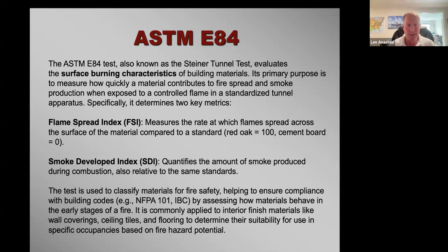And so what it does, you run the test and you get what's called a flame spread index, or FSI, and a smoke developed index, an SDI. These are the two criteria. For the flame spread index, the standard is red oak equals 100. I'm sorry, not 100 degrees. Red oak has a flame spread index of 100, and cement board is 0 because it doesn't burn.